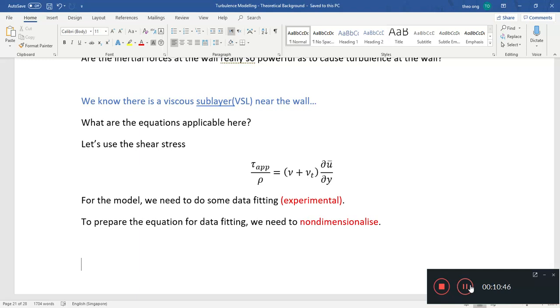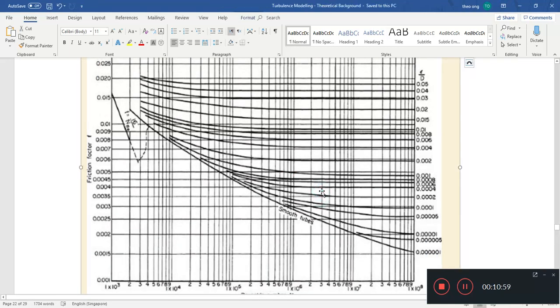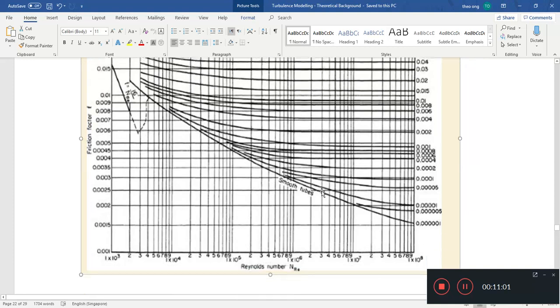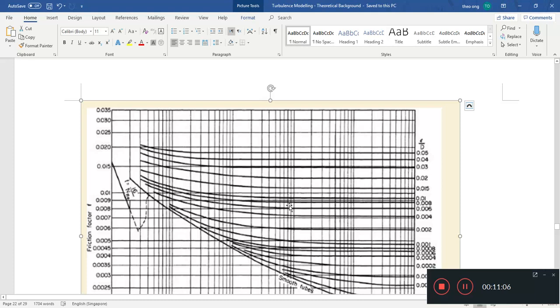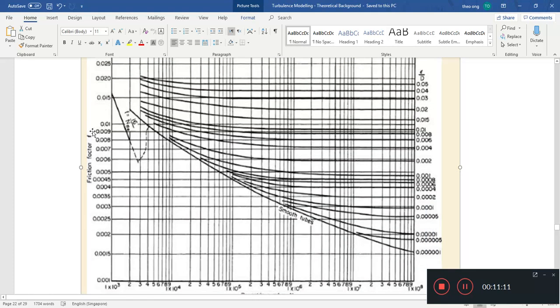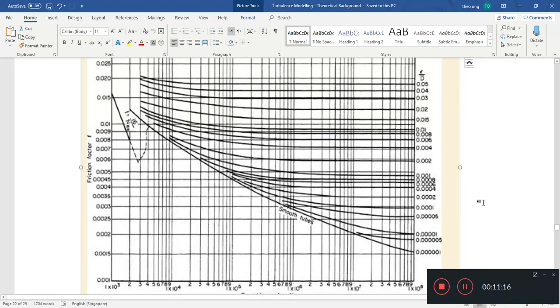These are non-dimensional quantities, and of course you have surface roughness as well, which will give you different kinds of curves. You recall this very common graph where we see the Fanning friction factor, or whatever kind, can be Darcy or Moody, compared against the Reynolds number, and for various surface roughness we have different values of the friction factor, so they have different curves.